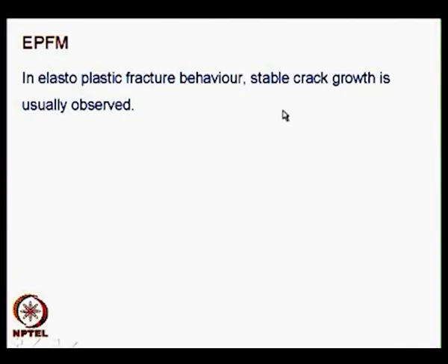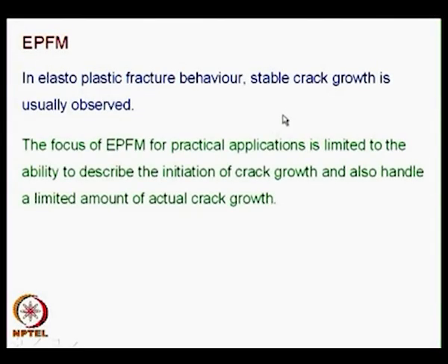So, you have to find out to what extent you can apply the concepts of J. The focus of EPFM for practical applications is limited to the ability to describe the initiation of crack growth and also handle a limited amount of actual crack growth. As long as you are able to predict the initiation, you are happy. You are not interested in studying further.